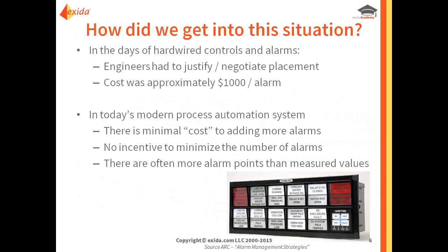So first, let's talk a little bit about how we got into this situation with all of these alarm management problems. If we think about the olden days in a typical control room, it was run by panel board control. So there was a limited amount of space on the walls for the panel board alarms to be displayed. So there was only a certain number of alarms that could be set up. So you better believe that there was a lot of thought put into what alarm should actually be configured, because there was limited space and there was a real cost to actually wire them up. Fast forward to today, the modern DCS, isn't technology great? It's actually taken things in the reverse direction. We tend to treat alarms as if they are free and don't give them a lot of thought as to whether we actually need them.